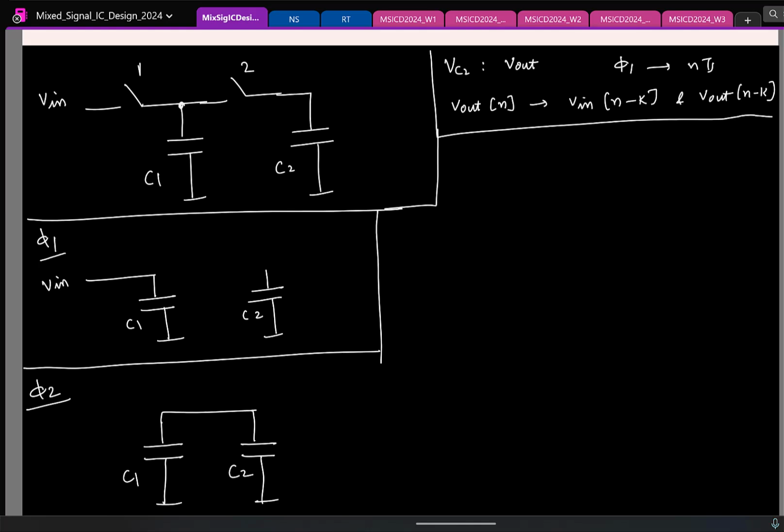Okay? Yeah. Clock phases, you can assume that those clock phases are not... Yes, absolutely. Because the point is, every clock phase is there to configure the circuit in one particular mode. You don't want to mix multiple modes at the same time. Yeah, that's a good point. So the equivalent circuit is fine.